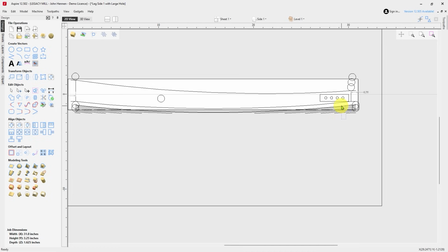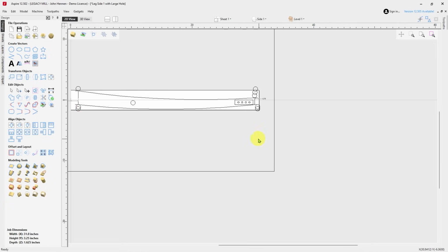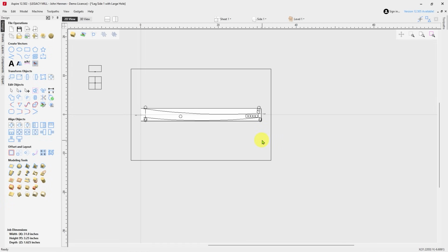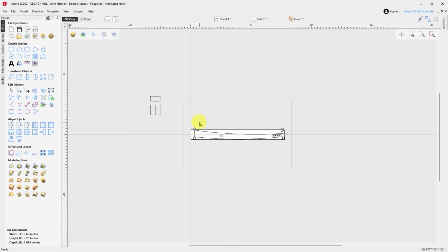So the first thing that I did is I decided on what cutter I was going to use. And on this one, in order to get a cutter long enough, I had to go to a 3/4 of an inch diameter cutter that had a cutting length of 3¼ inches, or exactly what I needed. I had to use the entire cutter, top to bottom. And when we did that one, we laid it out in a way that we could use what's called a swarf cut. And a swarf cut is when we're going to come down, then we're going to use the entire length of the cutting surface to slowly work our way in. So let's go ahead and lay all that out.